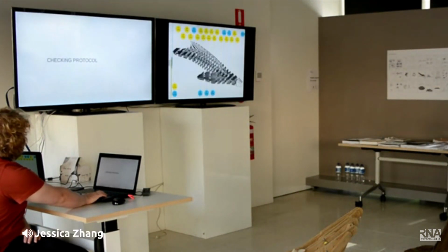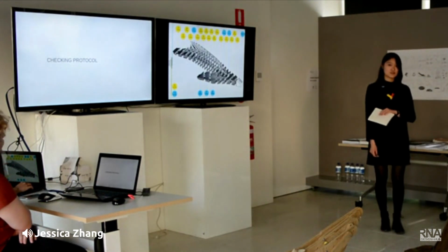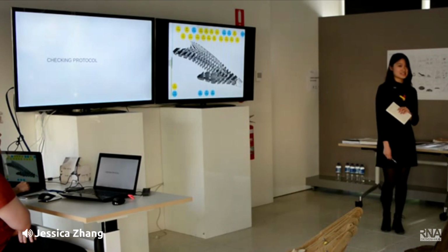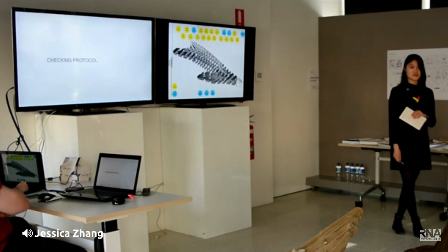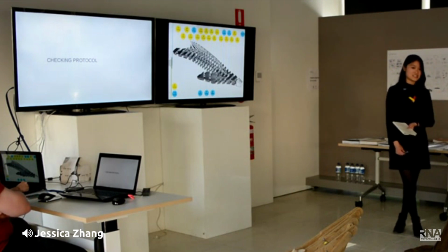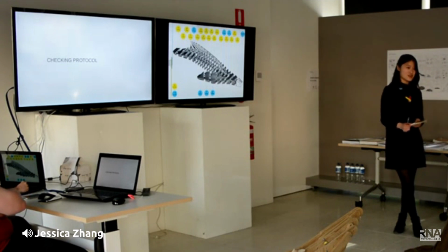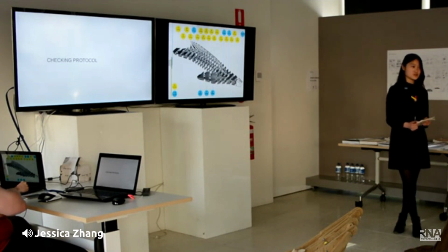Earlier, we intended to use 24mm hardwood ply, which weighs about 43 kilograms per sheet, exceeding the limit of 40 kilograms for 2 people to carry. Therefore, from OH&S studies, we decided to reduce the thickness to 18mm plywood, which weighs about 35 kilograms, sufficient for 2 people to carry.